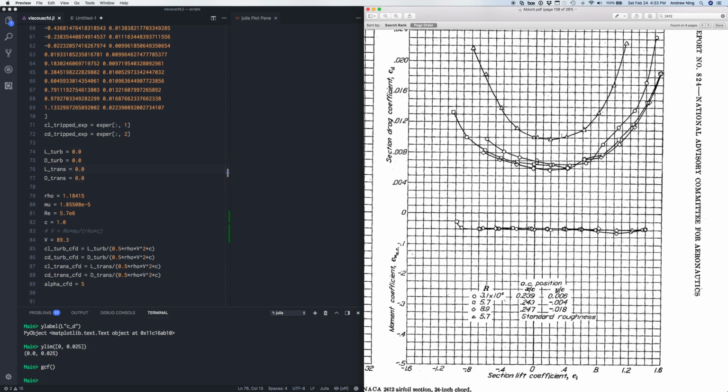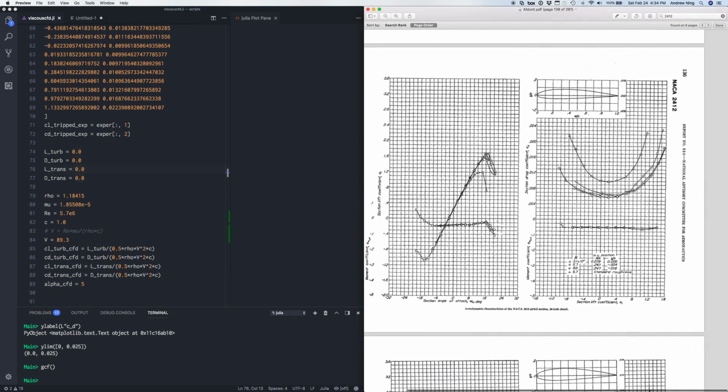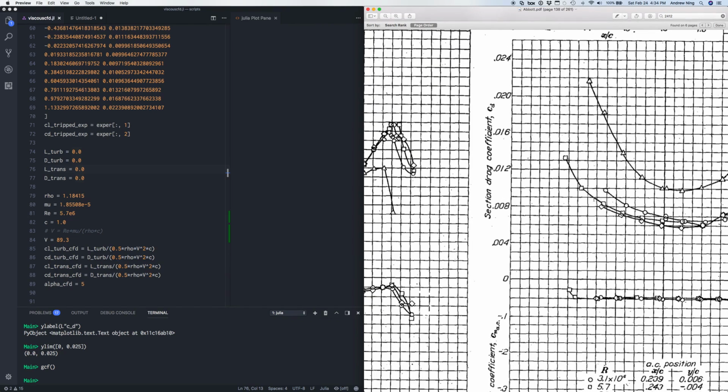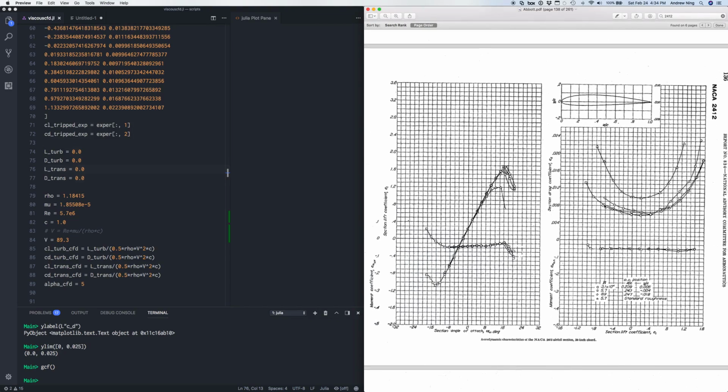So the current case I'm running with the Spalart-Allmaras is assuming fully turbulent, so it's comparable to this case. For the second scenario, I would need to use transition, and to do that, I have to use the k-omega model, and I chose the gamma transition model. I did that beforehand, and then I pulled all these points from the plot. I used a tool online called the Web Plot Digitizer. It makes it pretty easy to grab these data points.